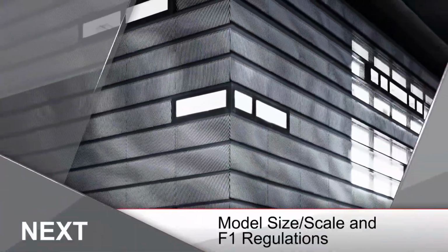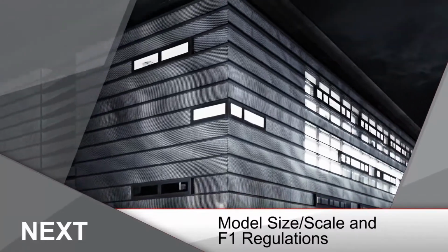After building this wind tunnel, we used to, while it was still permitted, really test quite often with a full-size car in the tunnel. If you have the money, why wouldn't you? The advantages were mainly that we were testing with real parts, full size, high speed, and that the car would then deform in a real way under aerodynamic load. And the main downside to that was the lack of a genuine cornering simulation, and also, honestly, the cost.